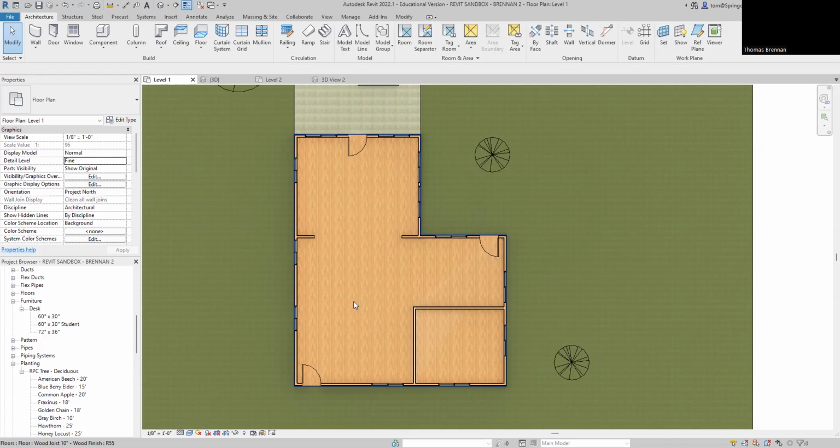Is there any way to get these windows to be the same distance from the wall? I'm going to put it in manually, but I also want it to be equal, according to the interior walls. I guess I can just do a middle distance to the side. One of the easiest ways to do it, there are a few different ways, but hit your escape key a couple times. Use a reference plane, remember, putting those lines where you want them. And then at that point, you can just adjust them as far as where you want them to go. Does that make sense?